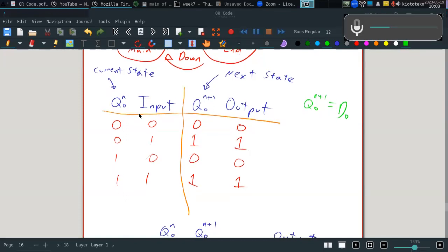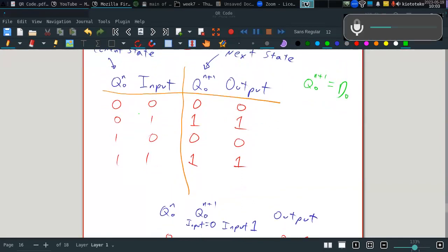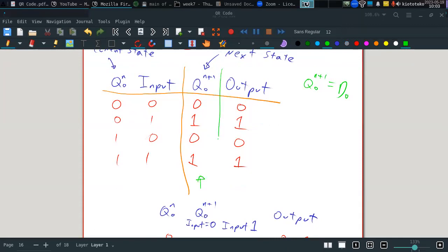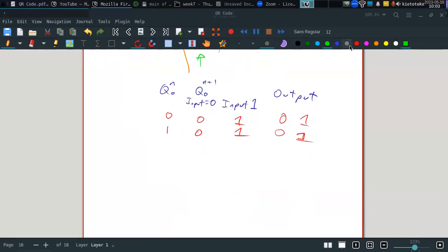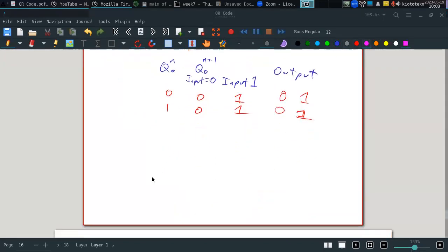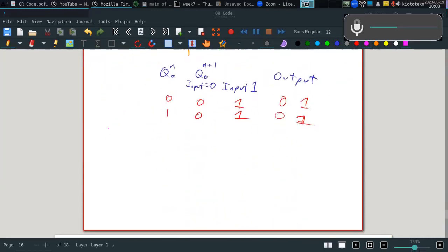And for this, we will try doing a Karnaugh map to just get the simple representation, because you can interpret this as a truth table that we need to simplify, no? Where we have our minterms here based on our input. So let's try doing that. We have 2 inputs and 1 output. So let's create the Karnaugh map here. Okay, let's see, Q0 and input.